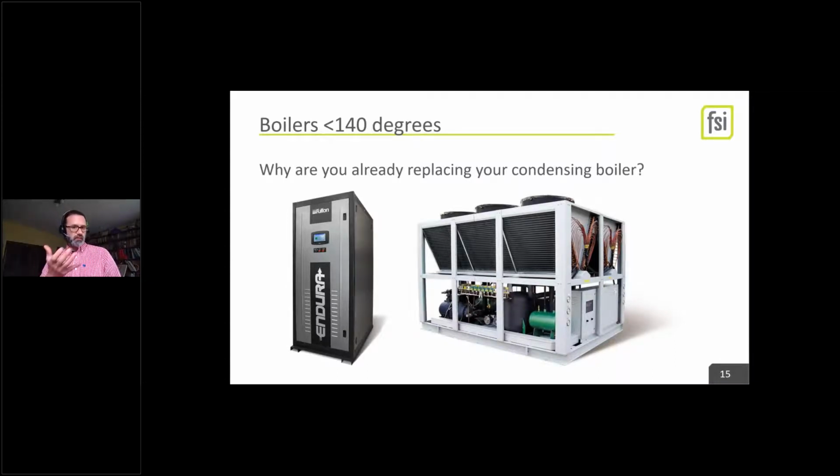Also consider that with the heat pump chiller, once you start doing that, you need to talk about refrigerant. And like we said, R410A is going away. R32 might work out really well because this is a closed, contained, small volume system. It depends on where this chiller sits.